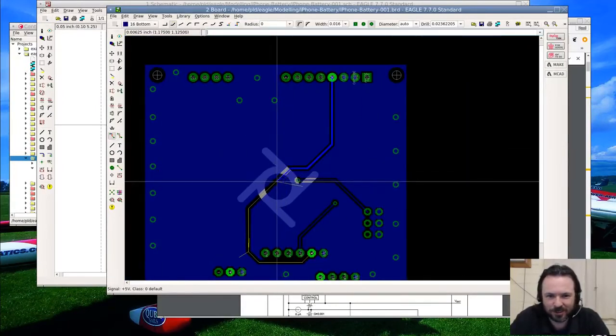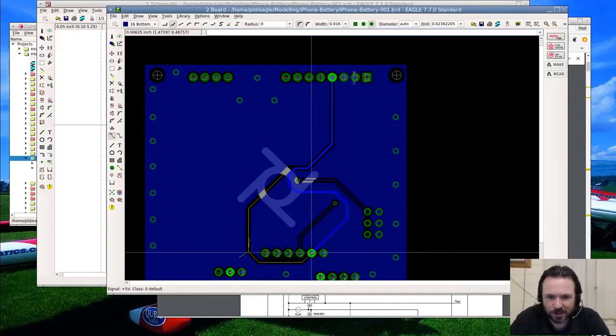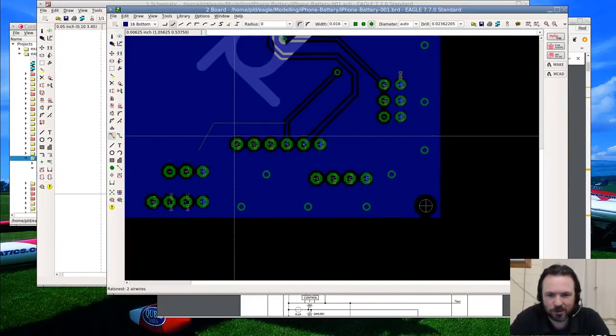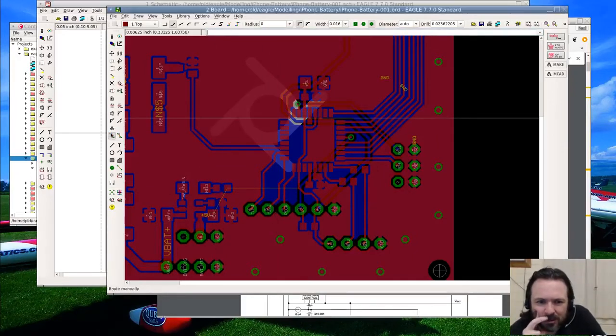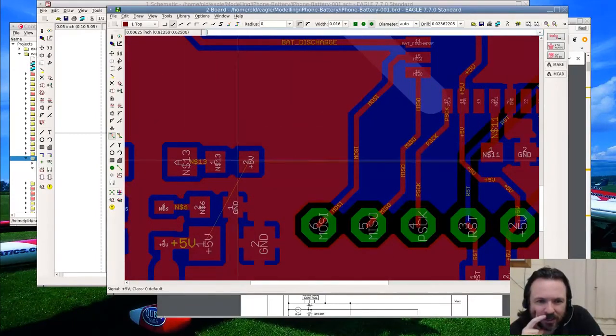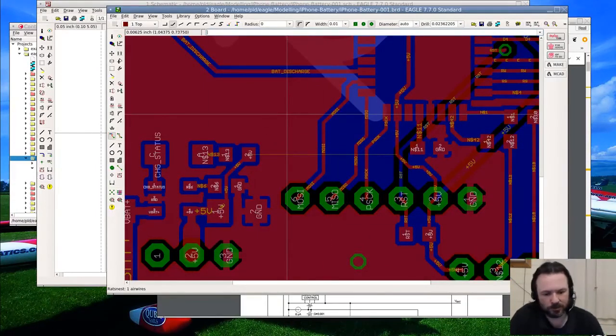Okay, let's go. And this is where Autodesk have added their improvement. They've got the follow me function. So as I walk through here, it would actually follow where I'm going and draw out a suitable trace based on your parameters. Okay, what are you? You're also 5 volts. Well, why didn't you... weird. Why are you doing this to me? It's because you want to be connected. What are you? You're the 2K, so we'll drop down to 10 thou trace and be naughty. Okay. And this here should just go to here. To the bottom of the board.